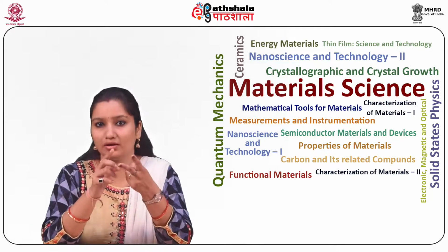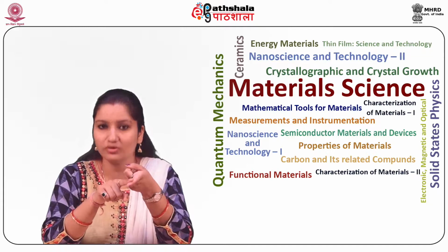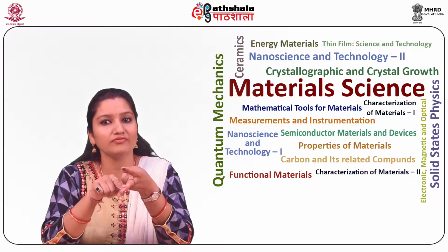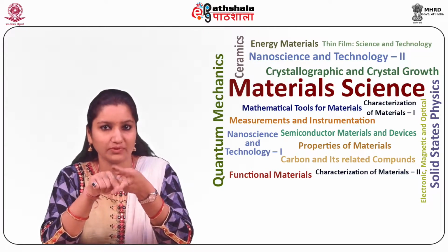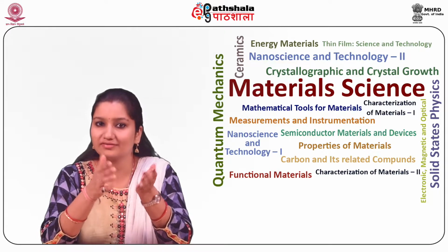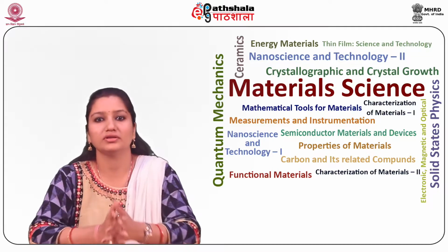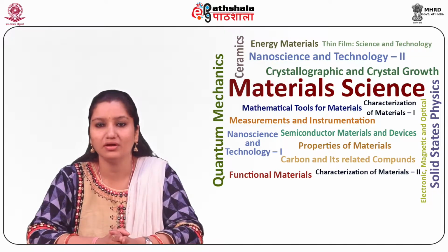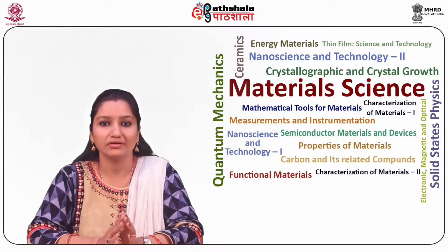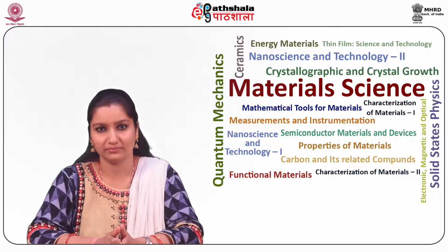There are two parallel electrodes in the system. The first one is the grounded electrode and the second one is the RF energized electrode. This capacitive coupling between the electrodes excites the reactant gases into plasma, which then induces a chemical reaction and results in the reaction product, which is then deposited at the substrate.